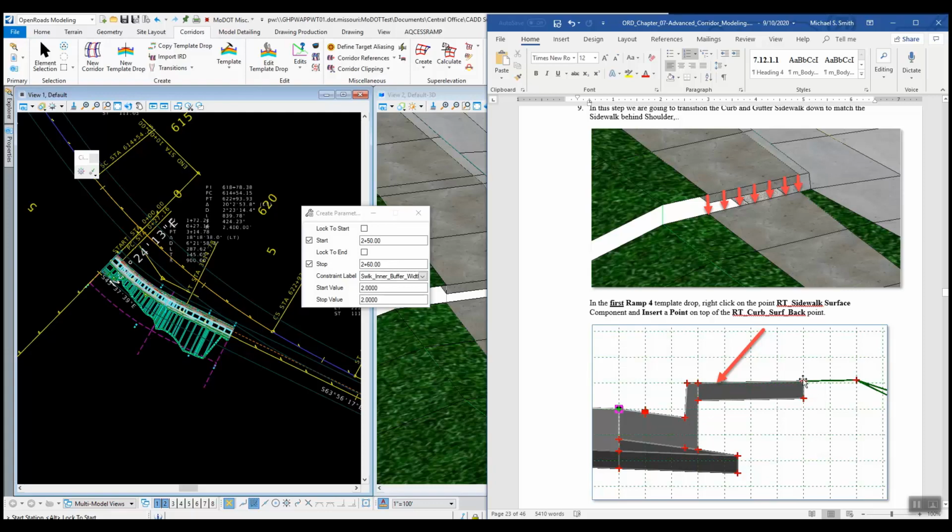So usually it's that point right there. We'll need to adjust to have it look at the new point instead of the top of the curb. Otherwise, when you slide this down, it's not going to move this point, and you'll have a large sloped sidewalk right through there. Not ADA compliant. So that's what we're going to do here.